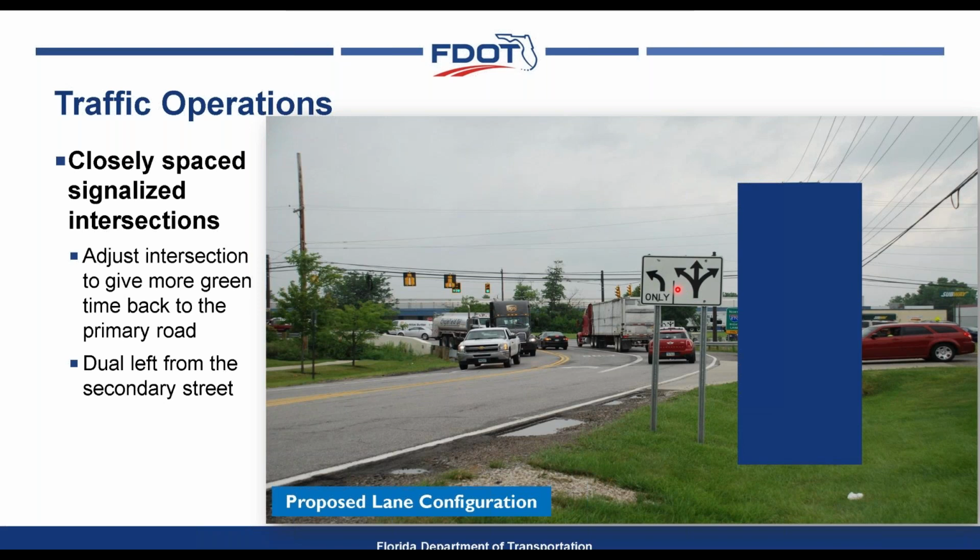It also allows a smaller green time to serve that movement, which can then be given back to the major street and help with the progression through the corridor.